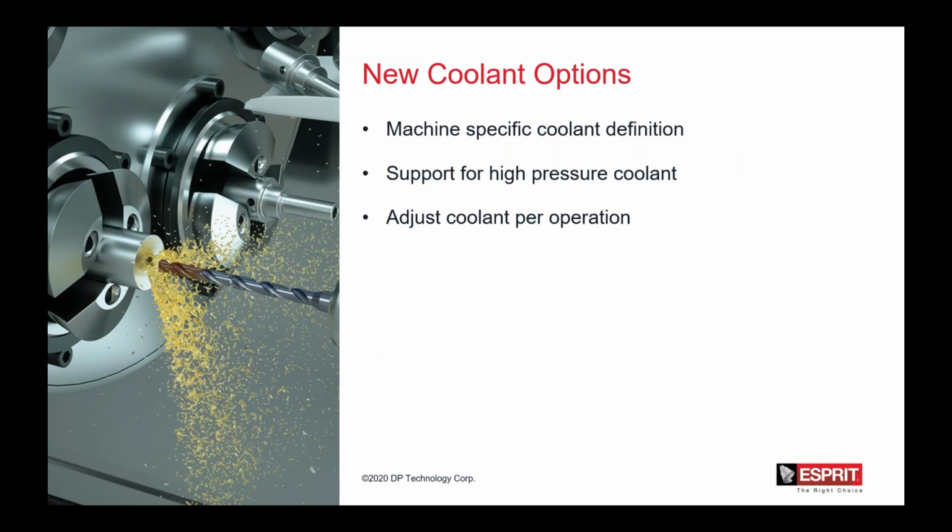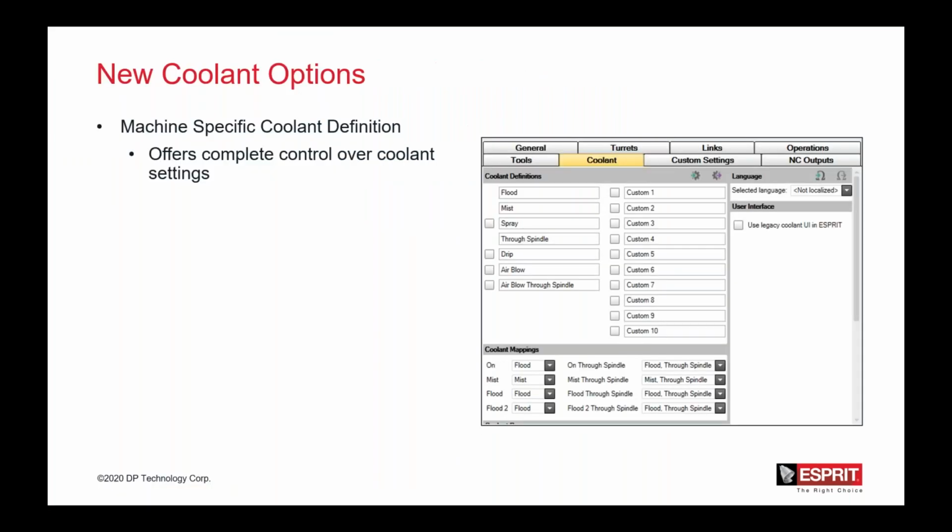And another improvement with Esprit is our new coolant options. So we are fully supporting machine-specific coolant definitions. There's full support for high pressure coolant, and then also you can adjust coolant per operation now, which is really nice. So what you see here is when we are creating these machine files, this is a view of part